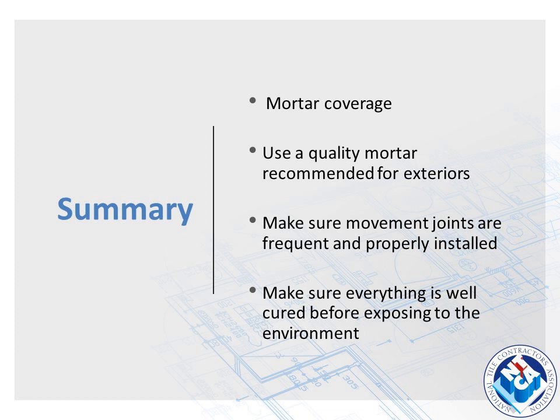Make sure you've got mortar coverage. Spot bonding is not acceptable with cementitious mortars, period. You must have 95% coverage. Check that at the beginning of your installation, lift the tile back off, and check it a few other times to make sure you're achieving good coverage and that your methods are solid.